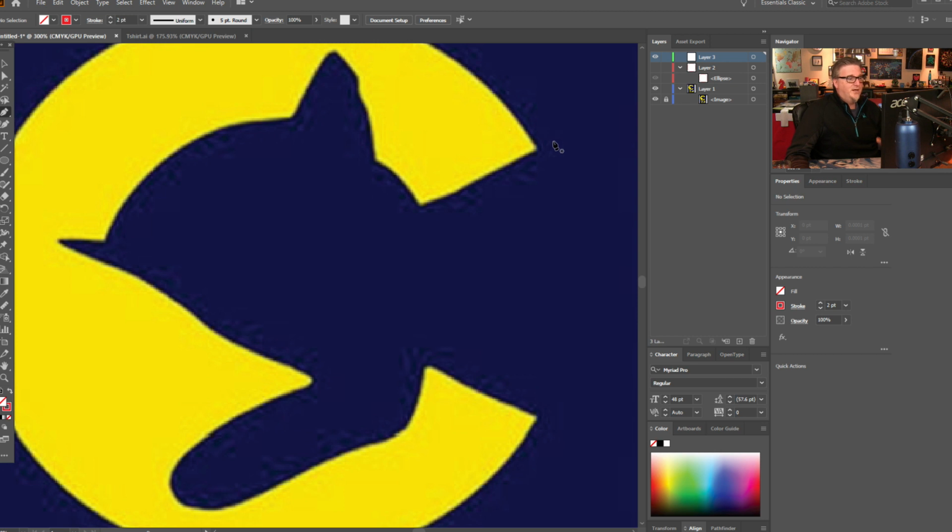So let's trace. Now, all I'm going to do is just make points. You can trace one of two ways. If you're really good with the pen tool, you can probably make this happen and do things with it. I'm not that good with it. So I'm going to just start clicking. And I'm going to click wherever there's a corner. I want to click there. And if there's going to be a compound or complex path, I'm going to click there. So you're going to follow me around.